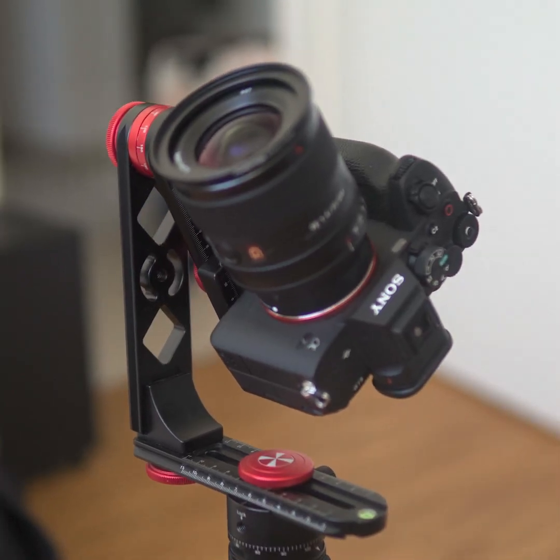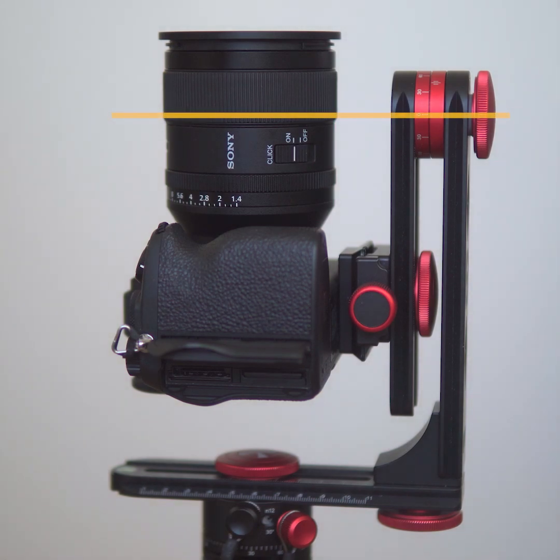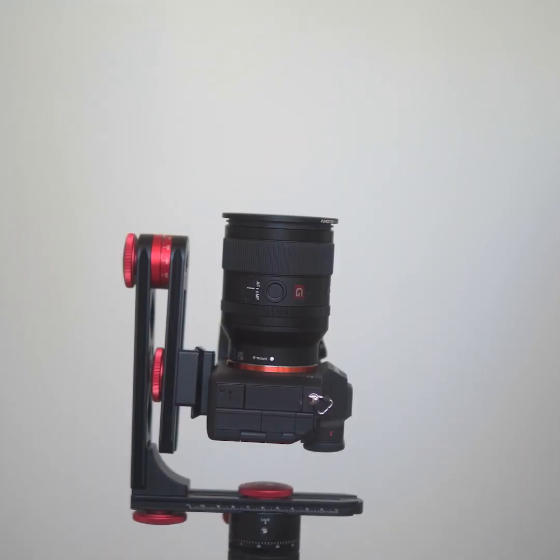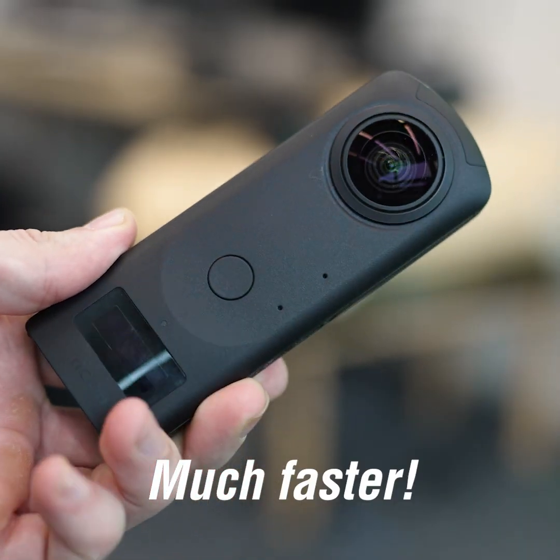But how do we actually get to do an HDR of the actual scene? There's two ways to do it. One is to get a DSLR with a panorama head. The camera is going to be rotating through the nodal point of the lens, so we get no parallax effect. Then you shoot from 4 to 16 images and you patch them all together. This way you get the best quality possible, and that's ideal if you are going to be looking at the HDRI directly. In this case, we are just gonna be using the lighting of the HDRI. A low quality HDR is more than enough to be able to illuminate the model. Therefore, we're going to be going the easier route, and we are going to be using a 360-degree Theta camera.